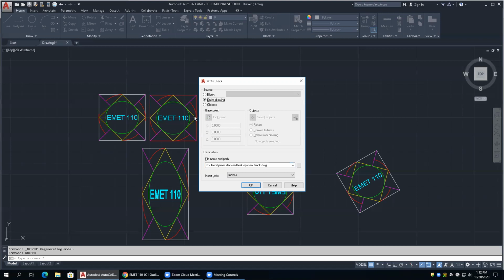So if you have all these layers, let's say you have 500 layers in that drawing and you're only using 5 of them, okay? When you WBlock that drawing out, it's going to lose 495 of those layers because they're not being used. So any unused linetype, any unused layer, any unused text style, any unused whatever, it purges it out. It cleans up your dirty laundry, okay?